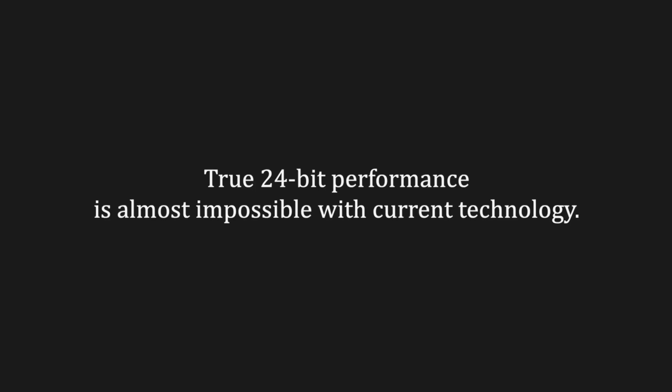Although many converters claim 24-bit resolution, true 24-bit performance is almost impossible with current technology. In theory, 24-bit audio would reach a noise floor near -145 decibels FS, equal to about 0.1 microvolt RMS, similar to the thermal noise of a small resistor.